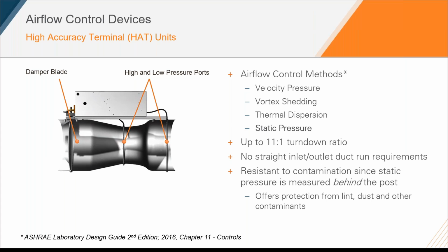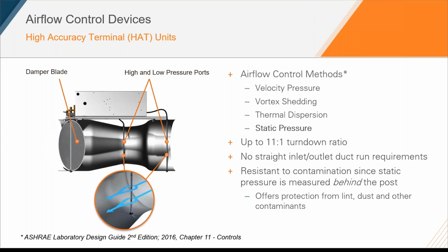The static pressure readings allow us to be a little bit more resistant to contamination. The reason is that we now have the static pressure ports facing downstream of the airflow direction, which gives us natural protection from lint, dust, and other contaminants causing issues with the reading.